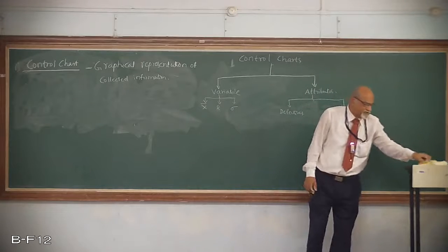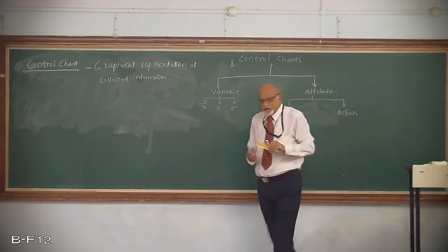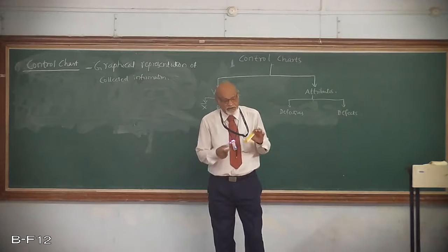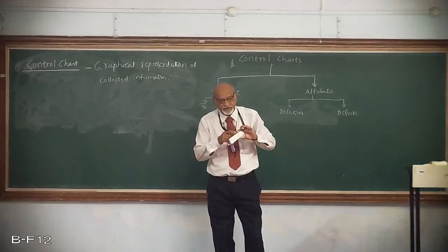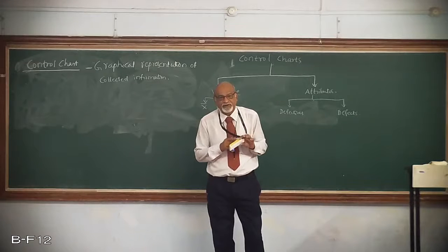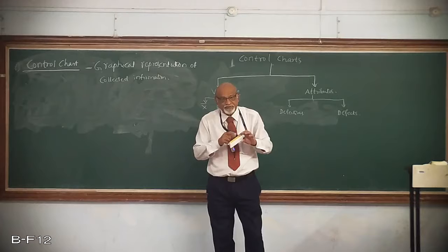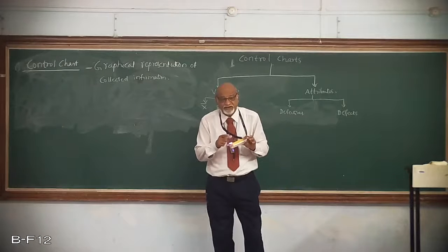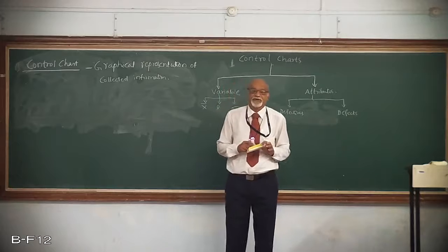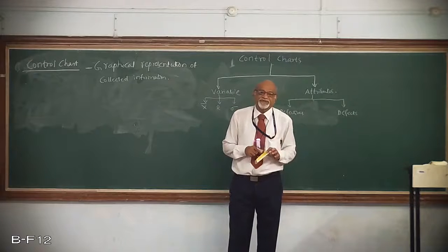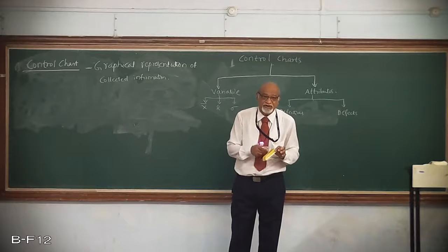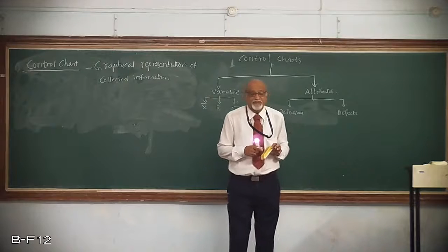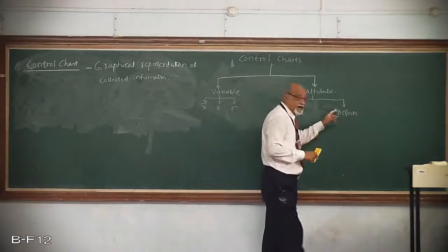For example, it might be accepted or rejected based on whether it has a particular width, whether it is meeting that particular standard or not. Thickness, length, breadth, surface finish, each individual instance, and the number of defects I can pinpoint, for example surface finish or blowholes or whatever we can think about. Those things I can specify.